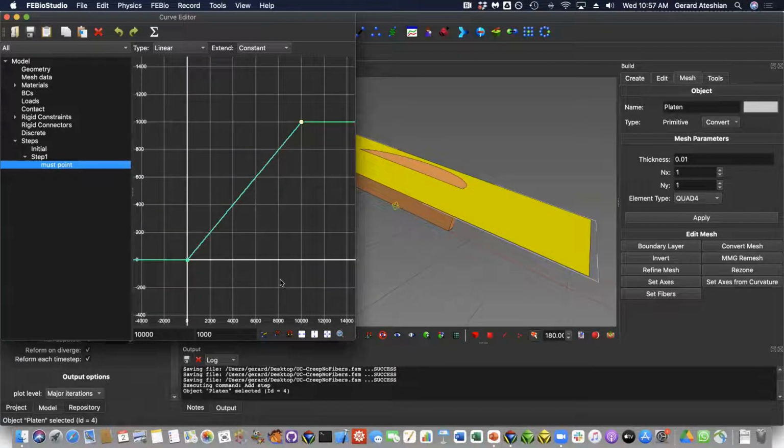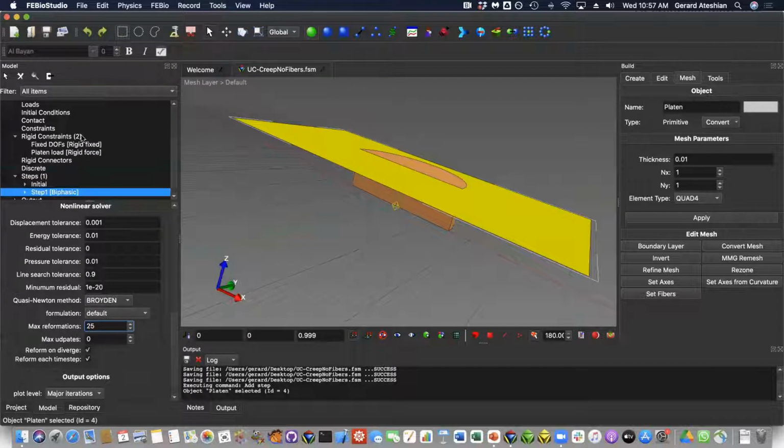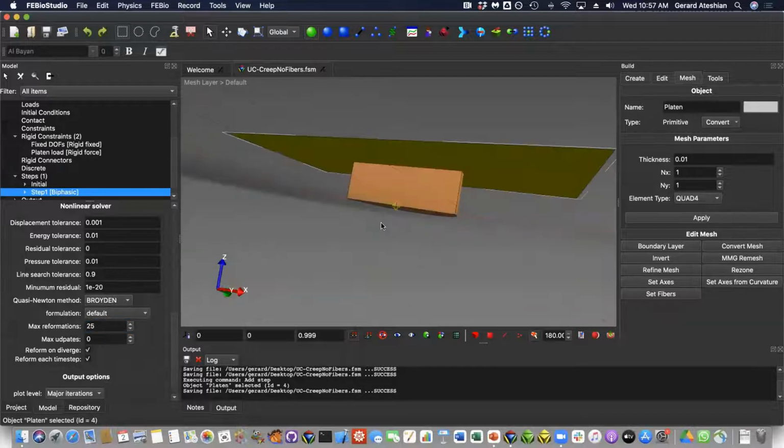So now what you see here is that as the analysis progresses, because it's a creep problem, I allow the time increments to increase accordingly. That means we're going to run much fewer than 100,000 time steps, which thankfully is the case. So now, in principle, I'm ready to solve, except that the one thing that I haven't done yet is to